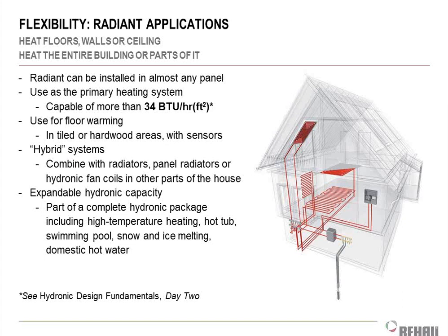And the reason for that is on a mild day when it's, say, 55 degrees outside, in the morning you may want to temper the air a little bit because it's kind of cool, but you don't want to turn on the full slab and wait 8 hours. So in those cooler seasons, it's nice to be able to run your air handler and do a little tempering. Plus, you probably need the air handler anyway for your ducted cooling system and for your ventilation needs. So sticking in a hydronic coil after you've already bought the air handler and ductwork and all that is a pretty minor expense in the grand scheme of things.